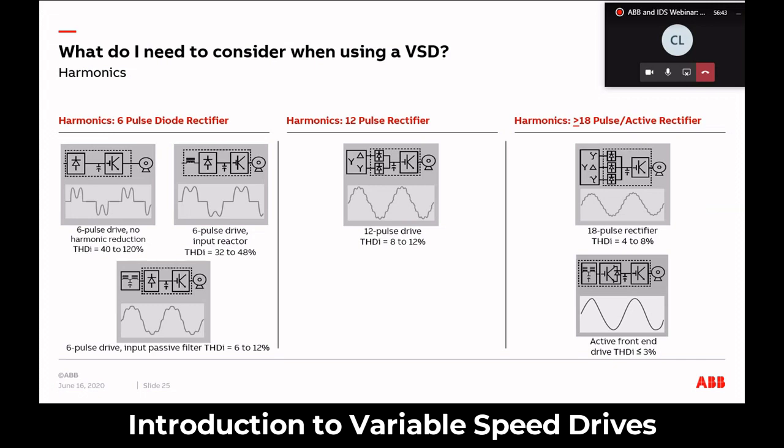There are other methods to reduce or mitigate harmonics on a system. We can go for multi-pulse or multi-phase systems, where instead of having a 6-diode pulse rectification, we can have either a 12 or 18 pulse, where we basically have an extra bank of diodes connected to different windings on the transformer, and as a result of that phase shift, we're able to cancel out certain harmonic orders.